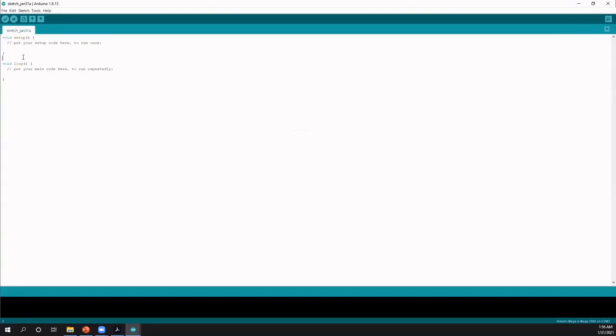You've also got some space between the two blocks that you can define variables that might be useful later on. This is the stuff that's going to run one time only. And then from that point on, what happens is the Arduino will enter this void loop. I don't know why they call it void necessarily, but this is basically just a loop that keeps going over and over again as fast as the Arduino can forever. And everything that you put in here will be repeated over and over again, unless you find some way to break the Arduino out of that.